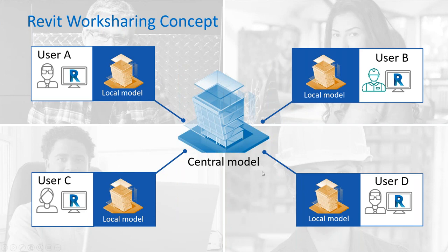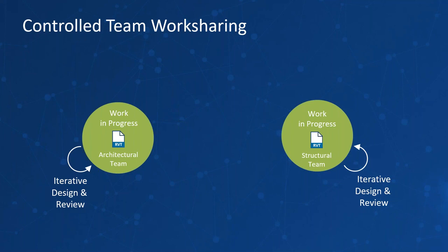Which is the first step to making it easy for people to use it, because if you've heard of the work sharing concept in the past, worksets, save to central, reload latest, relinquishing objects, and so on, well, that's basically the same in BIM 360 Design. There's a bit more functionality in there, which addresses what you see in this slide.